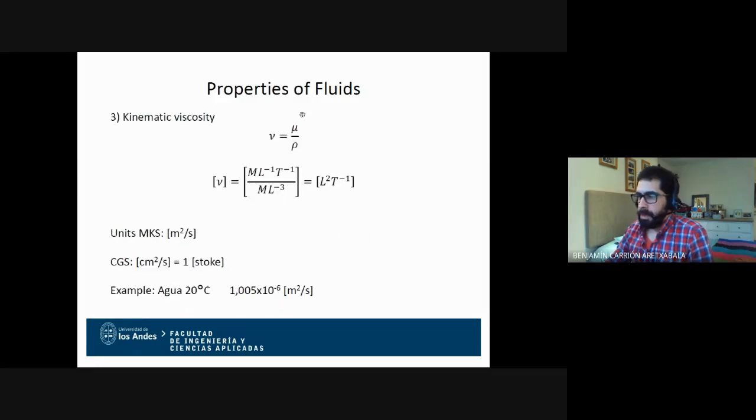And this is just a side note. If you divide the viscosity by the density, or the specific mass of the fluid, you get what is called the kinematic viscosity. It's kinematic because you remove the mass from it. It's only velocity related, and this is important, for instance, when you want to talk about turbulence and mixing. Normally both viscosity and density matter, so you can combine them into one parameter.